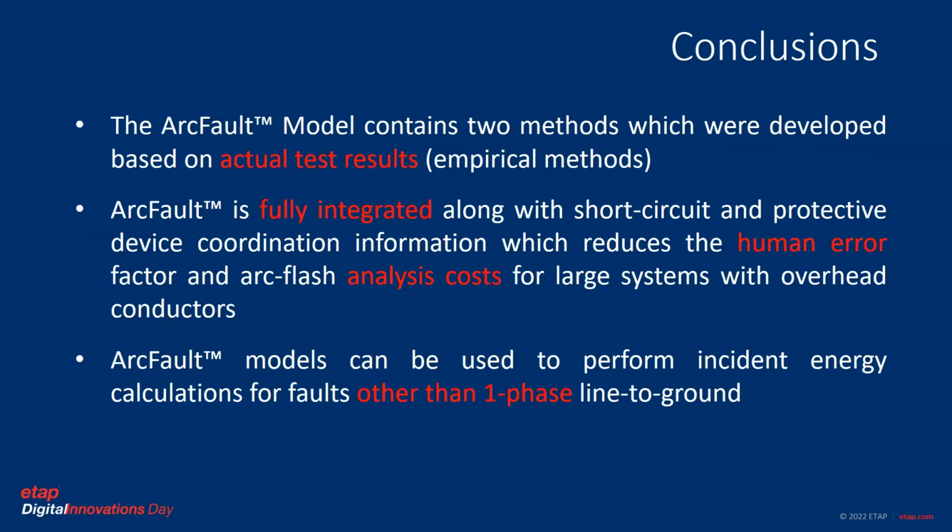We saw during the live demo that the ArcFault model contains two methods which were developed based on actual test results. And we saw that ArcFault is a fully integrated module along with the short circuit and protective device coordination, which will help us to reduce human error factors in the incident energy calculations. ArcFault models can be used to perform incident energy calculations for faults other than single phase line to ground, and such information is described in publications, including mine. So you could follow up and read on that application.